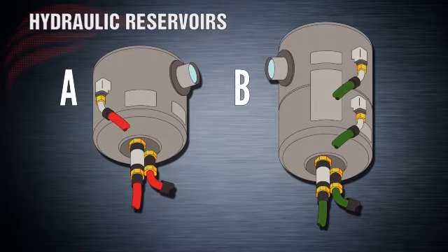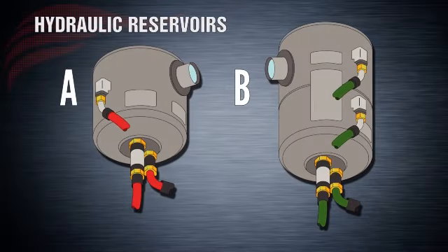Each hydraulic system has a reservoir that supplies hydraulic fluid under pressure to the hydraulic pumps. The hydraulic reservoirs are easily the most conspicuous pieces of equipment in the main landing gear wheel well, and they're located on the forward bulkhead. The reservoir center aft in the wheel well is for the standby hydraulic system, and we'll be discussing that later.